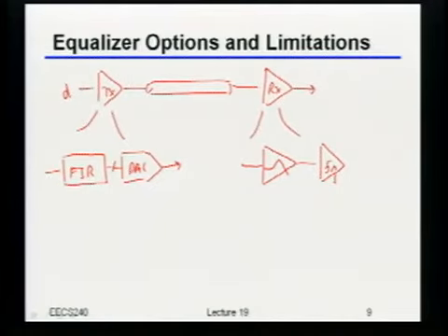So what did we say has to be sitting out at that output right there? What's the impedance that you have to be driving? Yeah, it's going to be something like 50 ohms, right? Anytime I drive 50 ohms, that basically says, if I want, let's say, a volt of swing, I need 20 milliamps of current. In other words, because this impedance is low, to get a certain voltage swing, I need to spend a lot of power for it.